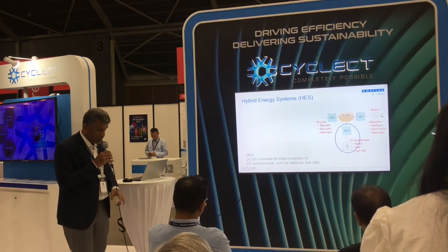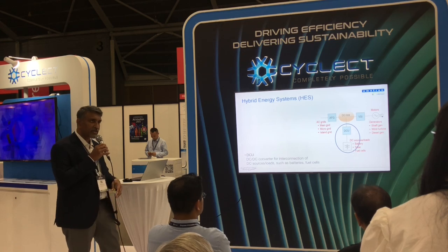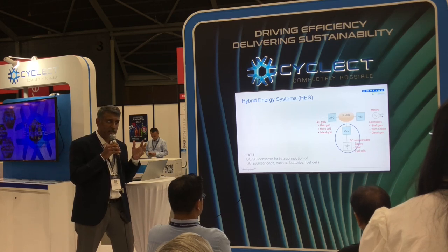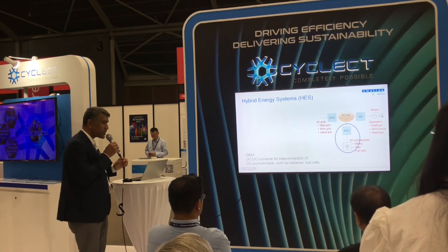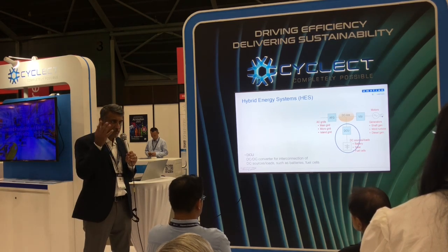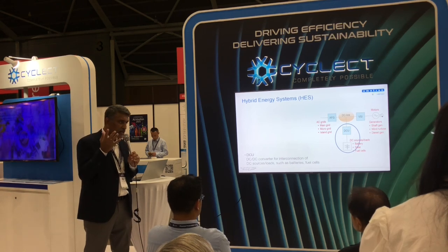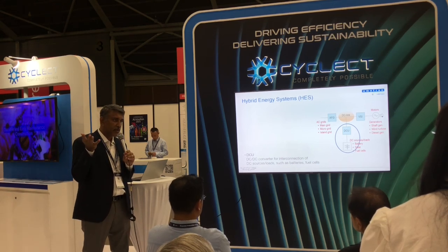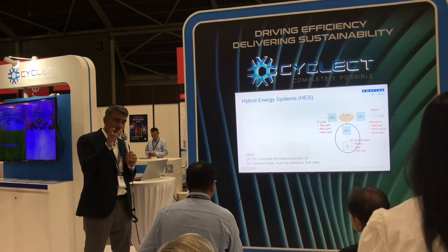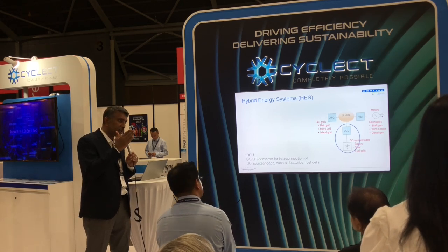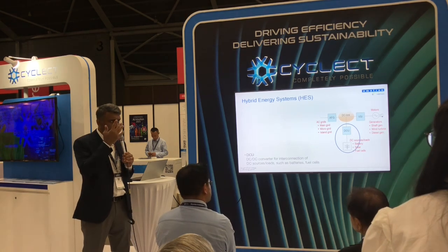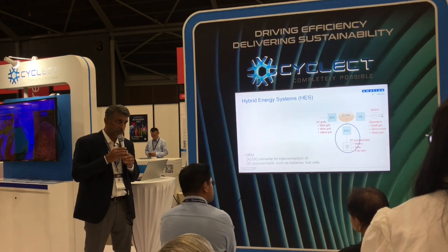But then I will talk to you more on the very interesting concept, the DCU, which is a DC to DC converter. Now you might ask me, why do you need a DC to DC converter? Okay, you need a DC to DC converter because we do not control the batteries. Battery is normally controlled by a battery manufacturer who can give you different ratings of batteries. His battery voltage could be different, while the voltage that you can generate is different. So then you use this device in between to basically interface between the voltage you can generate and what a battery voltage can generate. It's not just battery. You can see an example later on where there's also a fuel cell coming into it.